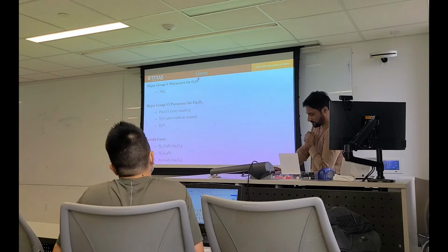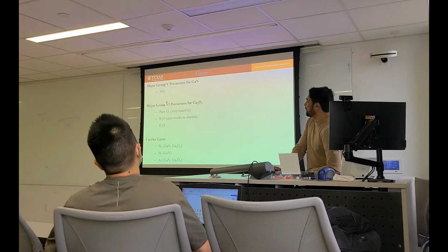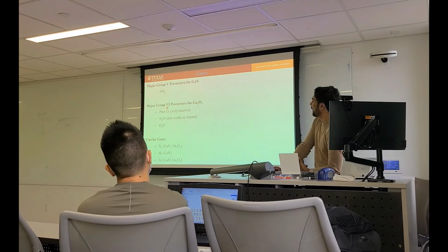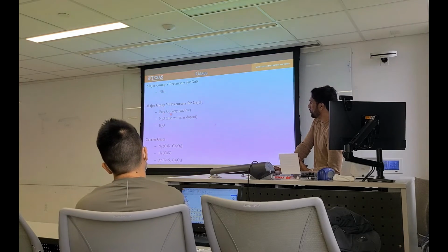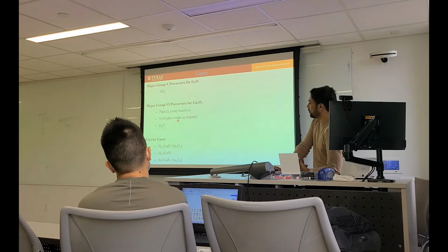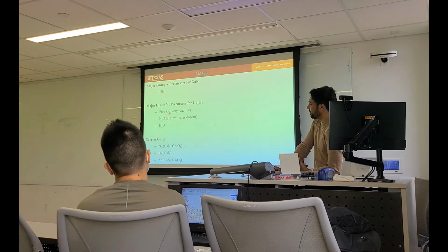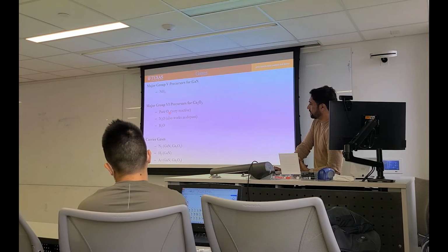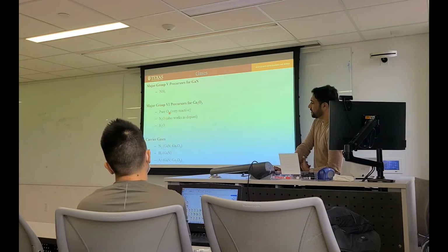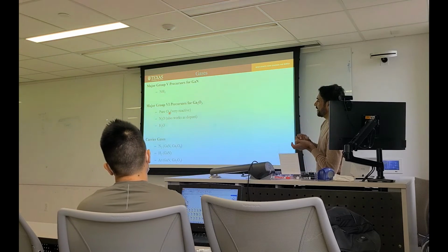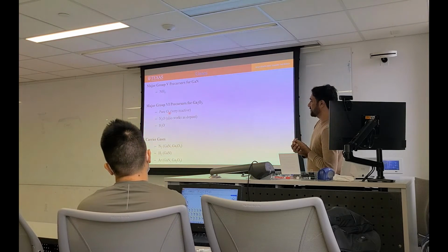We use ammonia gas for gallium nitride, which is well known, and for gallium oxide we use pure oxygen, N2O, or H2O. Pure oxygen is very reactive, but it gives very nice morphology. You need to work very hard to control its flow and to prevent premature gas phase reactions.